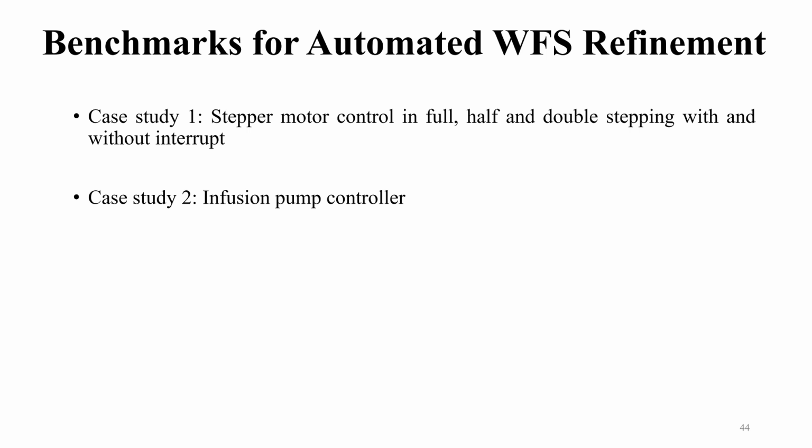We have used IARIA's 8100 LPV module infusion pump for our experiments. The IARIA's Medley pump uses pulse width modulation for dosage control. We implemented the pulse width modulation control for IARIA's pump on an ARM Cortex-M3 based LPC 1768 microcontroller, which was interfaced with the pump so that the code implementation can control the pump. We have also taken the formal specifications for the pump control software based on requirements from another paper that has been published.